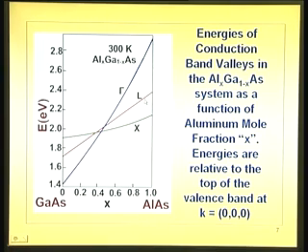Now, there are other lines which are coming up, that is this x line. X line is actually along that 1 0 0 direction. Okay. So, if you see the x line, this is something like 1.9 or so, close to that. Okay. This is where you will see the band gap. Sometimes you will see in the literature, one is 0.35, other one is something like 0.5, but this is the one which is closer. When you look at the transition from here to here, you worry about that.